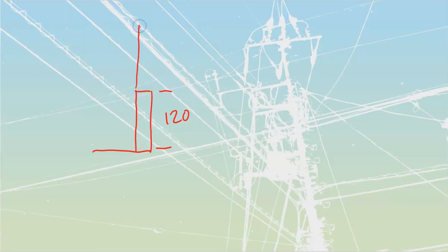Then above that, we are going to have a range that it's going to be able to take care of. And then this peak over here is going to be my MCOV. Now this thing could be quite a ways up over there. Let's say that this one is 2400 volts. What this is, and you should have added that word not, is the AC or DC voltage above which the SPD will not provide clamping.